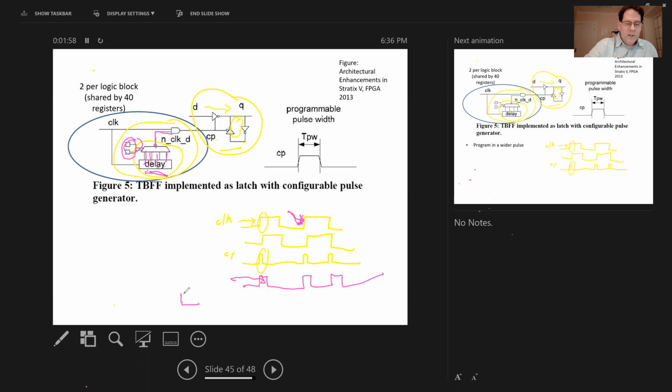So I've got a register here. It goes through some logic, goes to another register, and it goes through some more logic, and it goes through another register. Let's say that the delay of this whole path is currently 4.5 nanoseconds. And let's say the delay of this whole path is only 3.5 nanoseconds. And let's say that I want to hit a clock period of 4 nanoseconds. So I have some extra time on this side, but I have negative slack on the left-hand side.